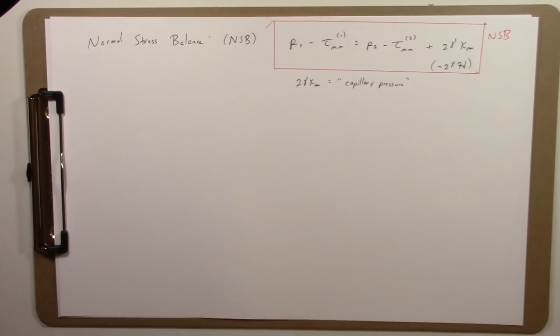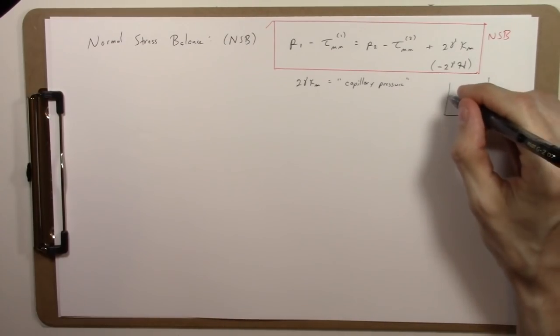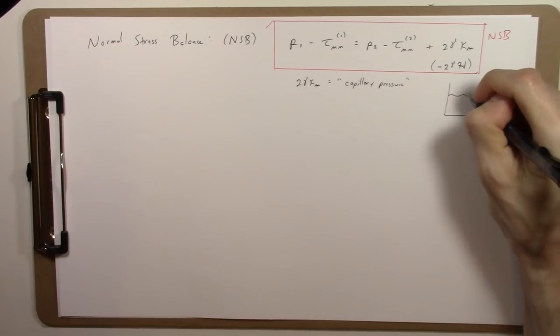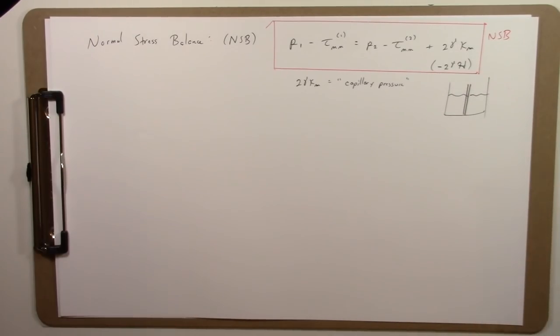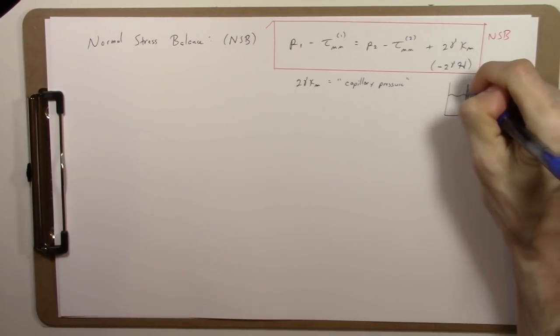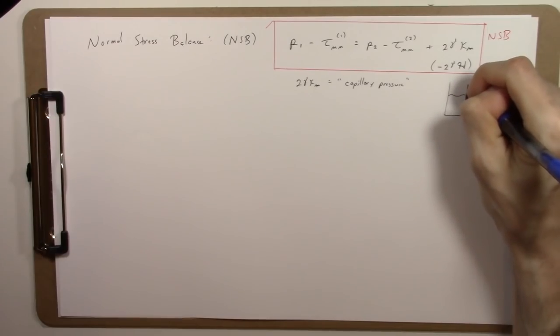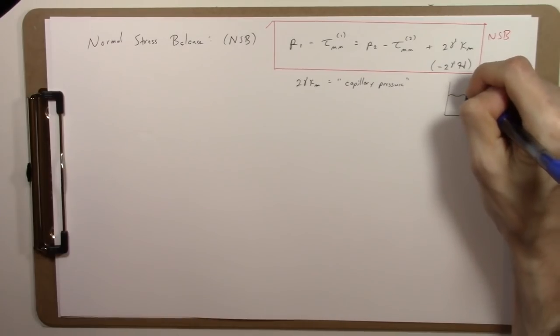The same thing can happen if you have a very thin tube immersed in a container of fluid. Let's say we have a container of liquid. We put in this very thin capillary tube or very thin straw. The question is what happens? Well, you'll find you have a meniscus here that's curved downward, and so in fact the fluid will fill the very thin straw or capillary tube to a height that's greater than the height of the surrounding liquid.